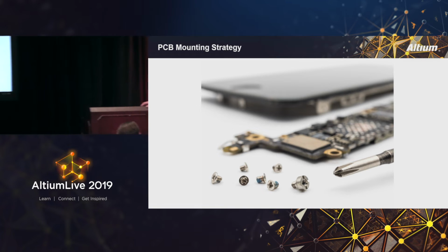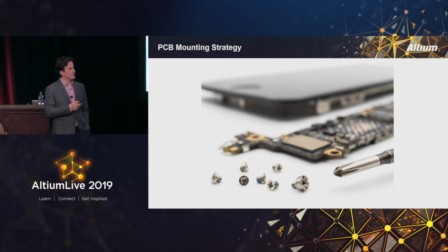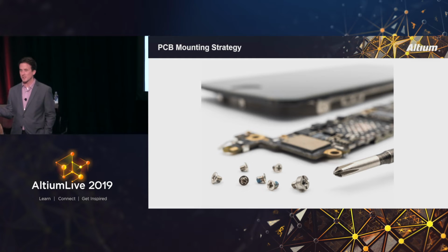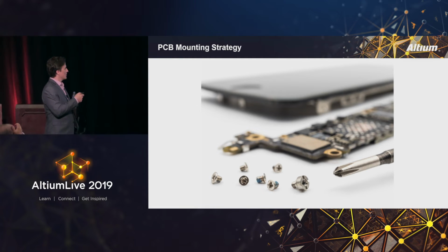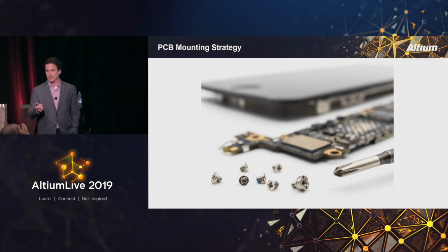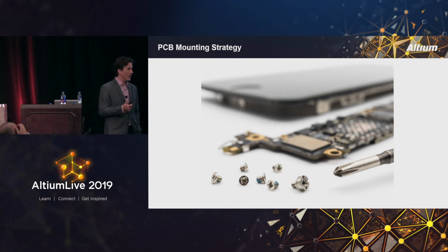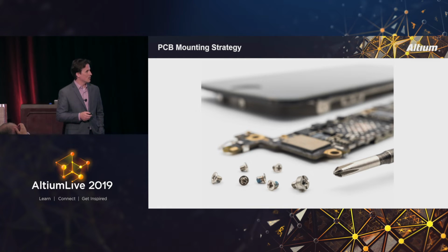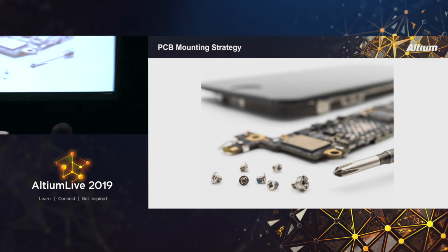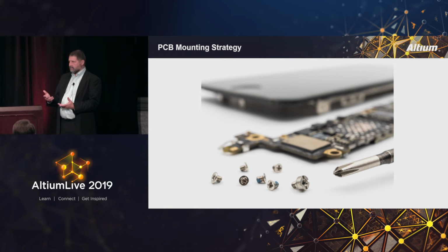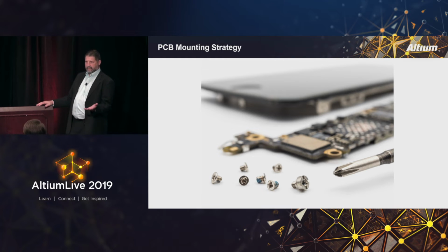Mounting strategy. I think this is something that's kind of overlooked, and something I've learned on the fly in my job. But there are, obviously, screws. I mean, that's pretty straightforward. Another common mounting strategy is heat staking, which is challenging to say the least. Yeah, you also have PEMs. You also have solderable screw connections, where you solder a part on and then you can screw into that. If you're going to have a daughter board on a motherboard, you might have something like that.